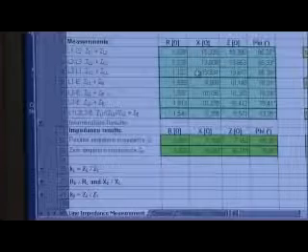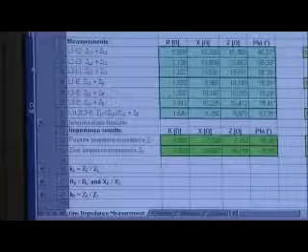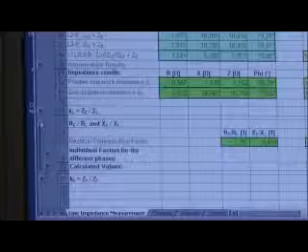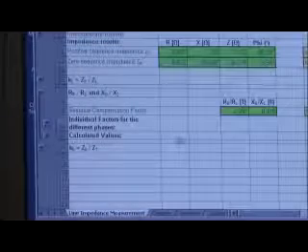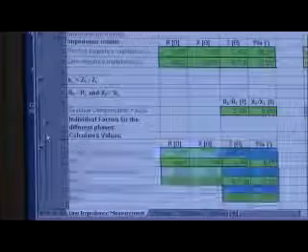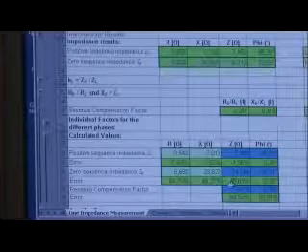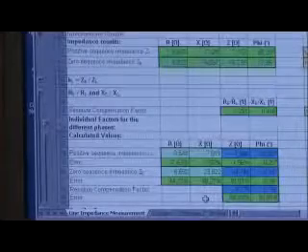As an example, a large utility requested our device for measuring the parameters to calculate the K factor of a line where zone overreaches had occurred. The measurements showed that whereas the positive sequence impedance matched within a few percent, the imaginary part of the zero sequence impedance was measured with an error of 48%, 16.1 instead of 23.8 ohms.